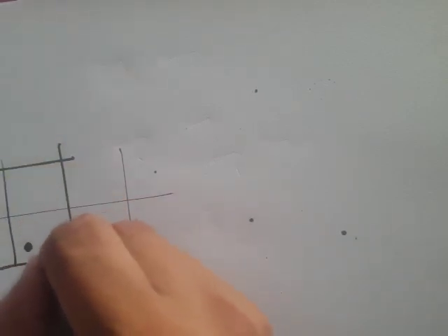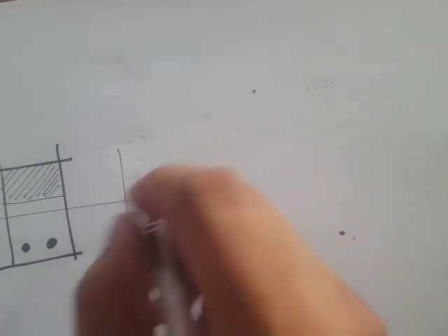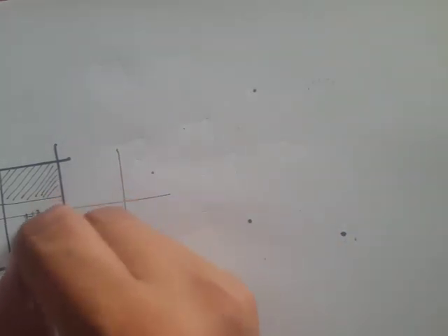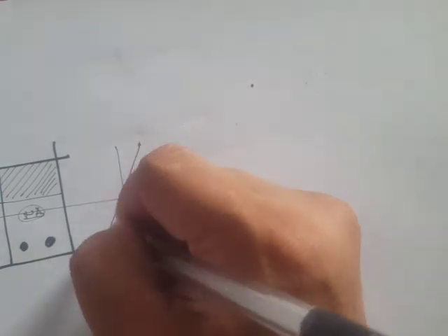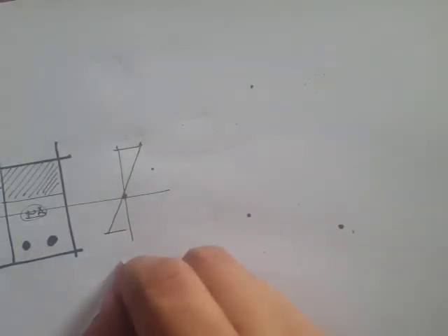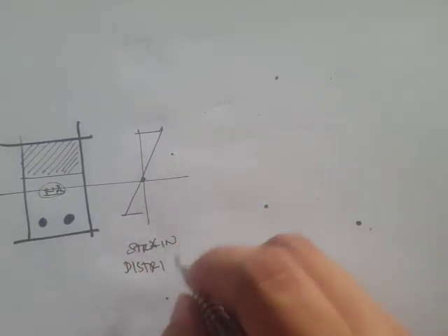Okay, so now let's draw again this section of beam, but now we'll show the strains instead of stresses. Okay, so we have this steel area here, and then our compression area. So this is our neutral axis. Okay, so the strain distribution in reinforcing steel and concrete is assumed to be directly proportional. Okay, so let's write it here, strain distribution, or let's say strain profile.